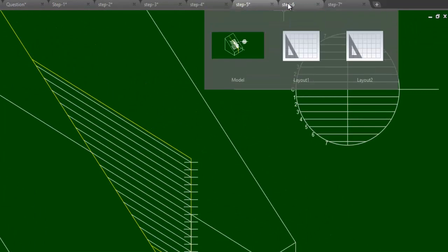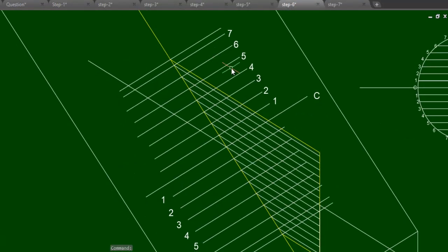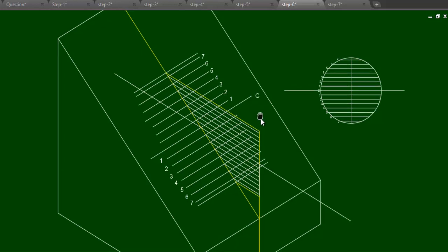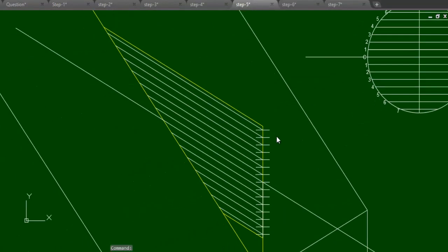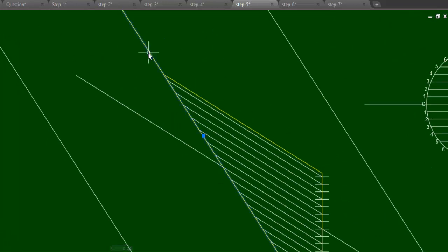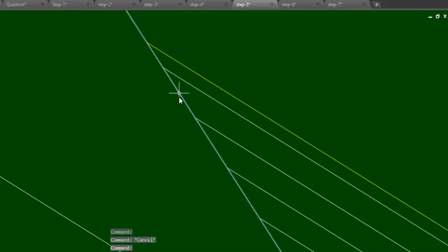In the next step, you see, this is the next step. So now the diagram is becoming more complex. Okay, so these are the steps actually we have to follow. We don't have any other option in the conventional method. Okay, what we had seen in the previous step, we have drawn these projections on this inclined plane up to here. Now we are getting these intersection points. These points we are getting on the inclined line or on the inclined plane. We have this point, this point, this point, these points.